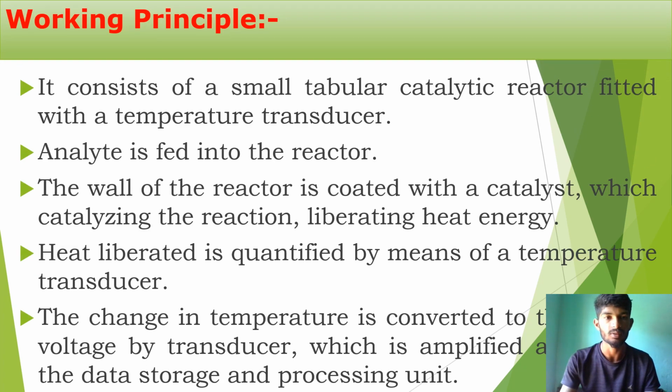Working principle of thermometric sensors. It consists of a small tubular catalytic reactor fitted with a temperature transducer. Analyte is fed into the reactor. The wall of the reactor is coated with a catalyst which catalyzes the reaction, liberating heat energy. The heat liberated is quantified by means of the temperature transducer. The change in temperature is converted to an output voltage by the transducer, which is amplified and fed to the data storage and processing unit.